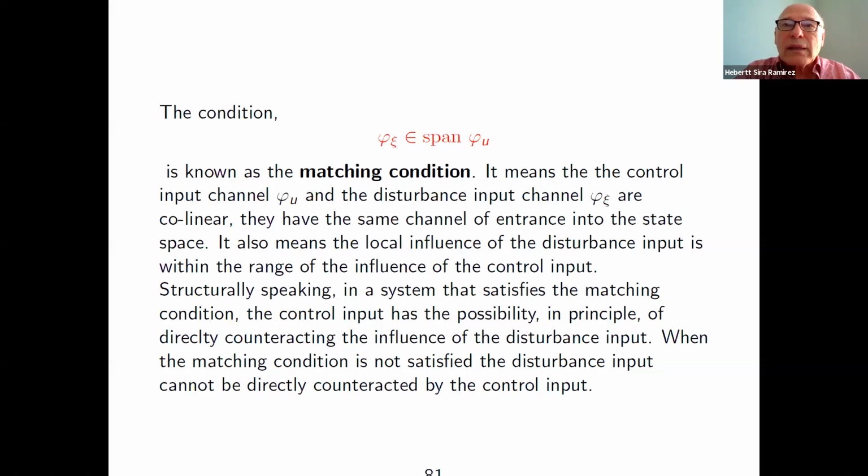Between the two there is an ideal transformer relationship. So if you take the mechanical torque and the electrical torque, they have to be numerically equal, right? So that there is no loss in the energy conversion. Well, possibly adding some friction torque. Yeah, the friction torque is present in the mechanical equation. Or part of the mechanical, yeah, okay, that's fine.